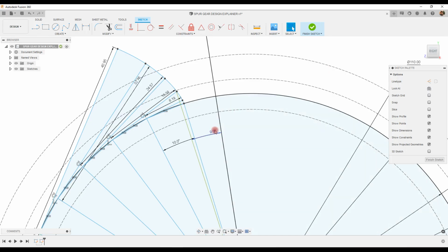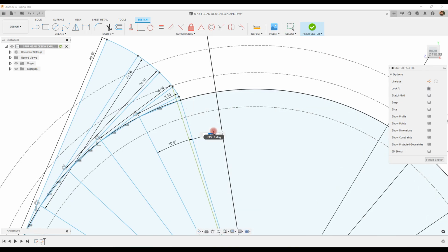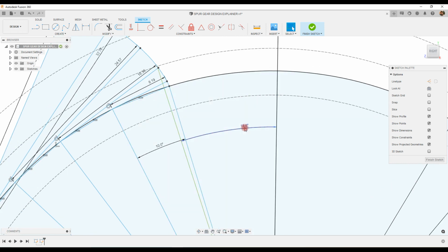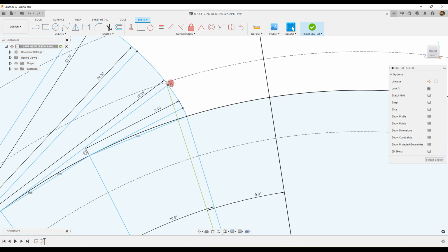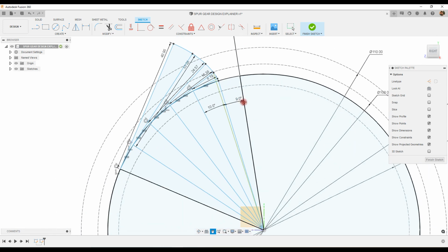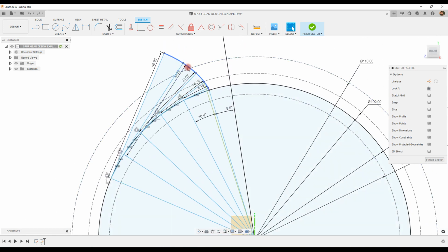Now going back to the CAD workspace. So this value of angle, which we had given earlier, it was 18.77. If we enter it as 9 degrees, this will indicate where this point will be located once the next tooth starts. So the corresponding location of this point over here will be over here. So now based on this, we can make a line to mirror this profile on the other side.